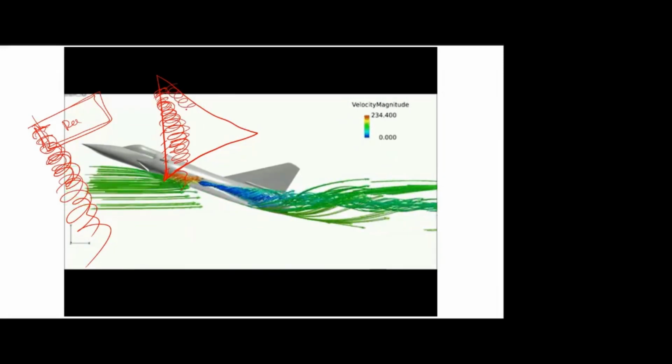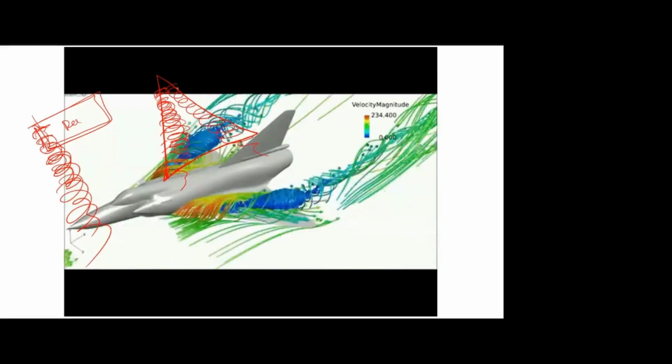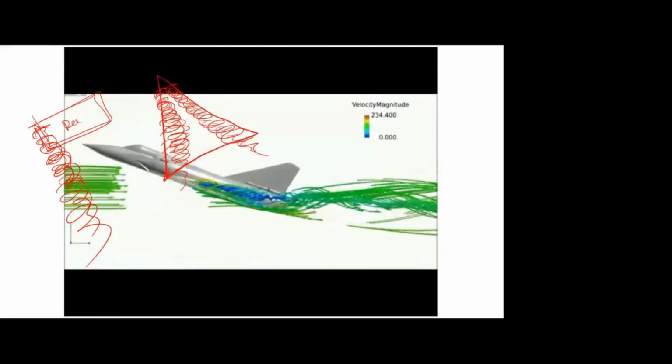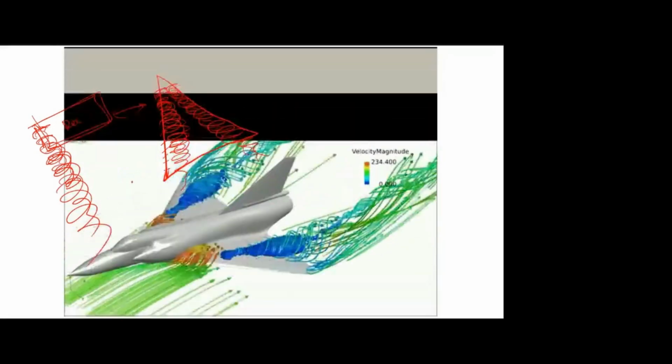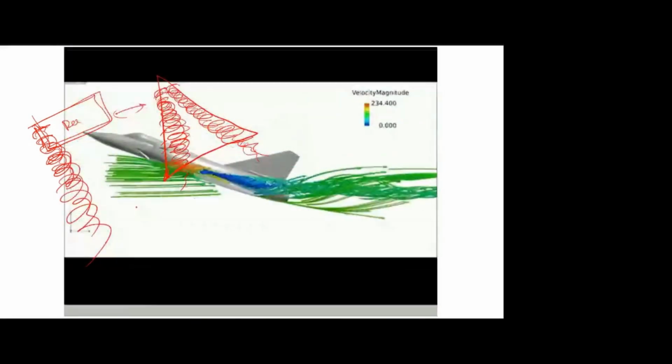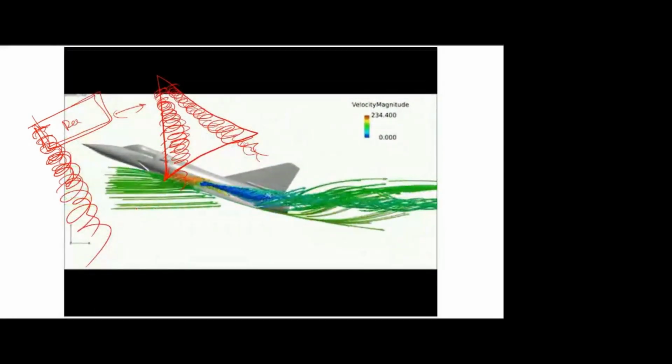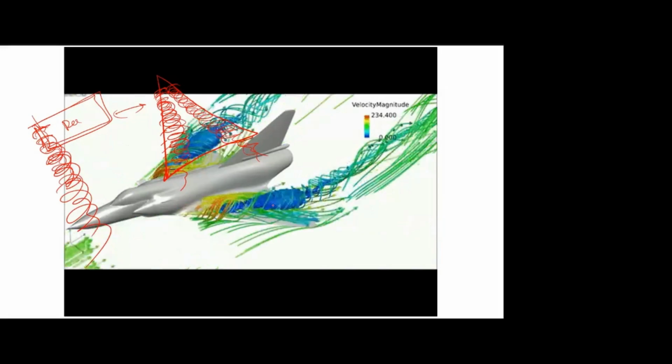On the delta wing, the side leakage flow becomes a vortex and that is visible on the wing itself, but in the rectangular wing, the vortices are formed only behind the wing. Is that a clear difference between rectangular and delta wing? So we don't have vortices on the rectangular wing, only for the delta wing. You can see the vortex structure.